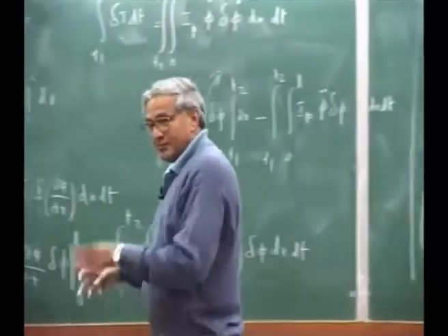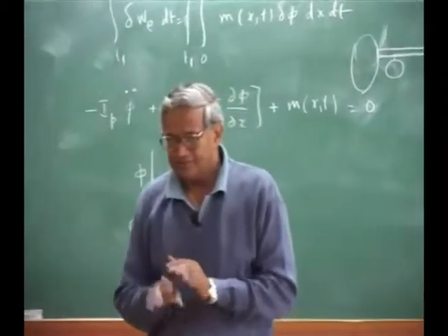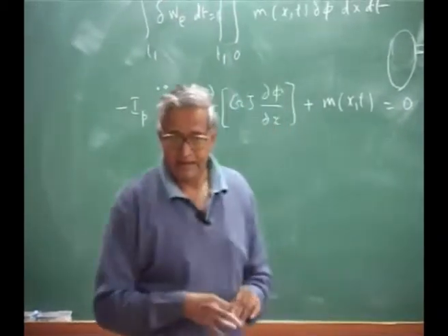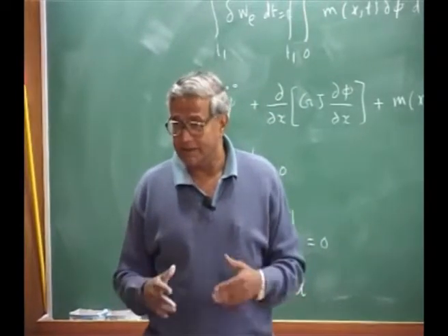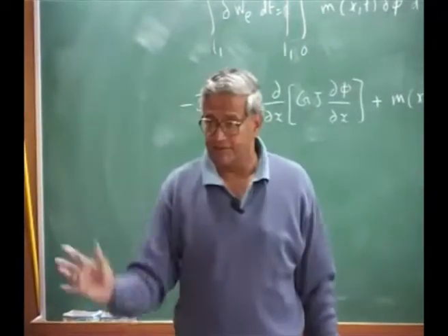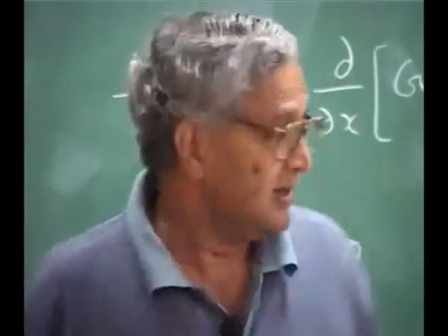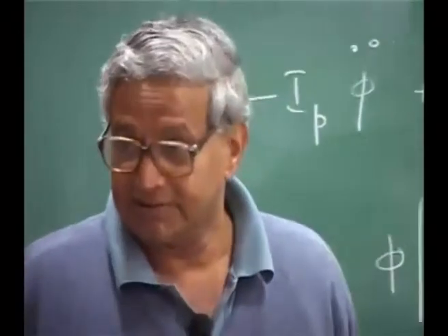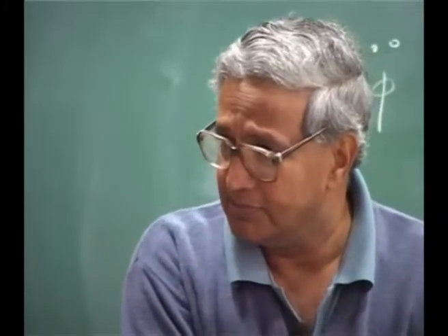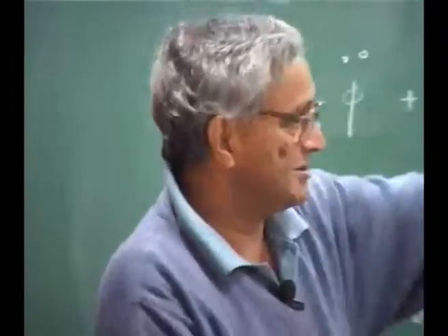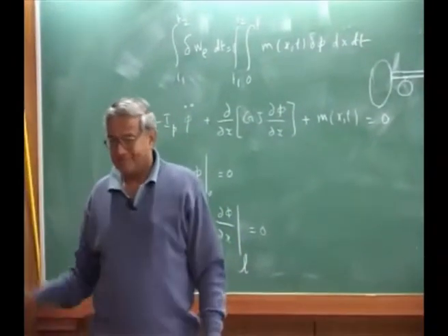Now the question is, for the static problem, I taught you one thing, you have learned that part, the Rayleigh-Ritz method of obtaining an approximate solution, because you cannot get a solution for any EI variation. Please remember here EI is a function of x. Similarly, GJ can be a function of x. So when you want to solve the static aeroelastic problem, that is one set. The time derivative is gone, and you solve the ordinary differential equation.